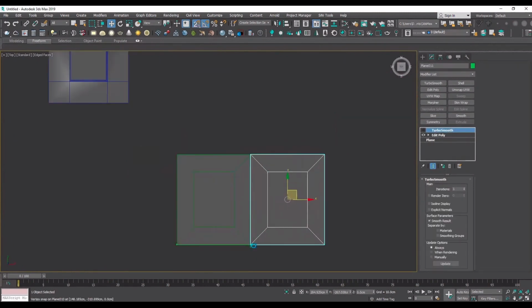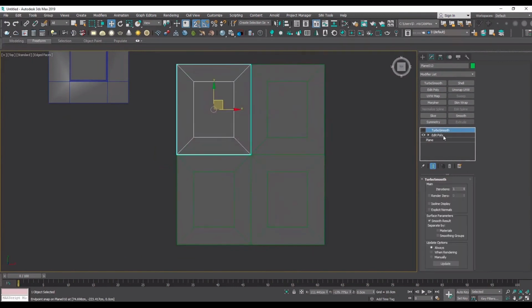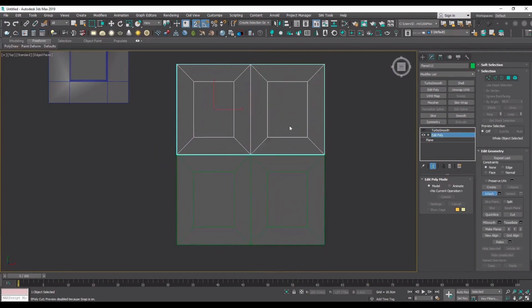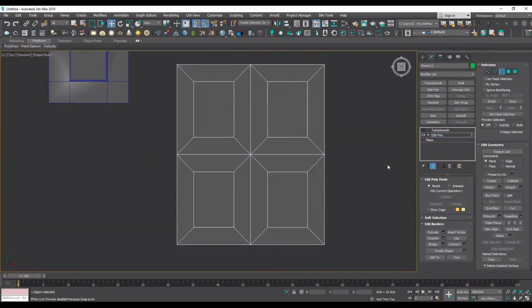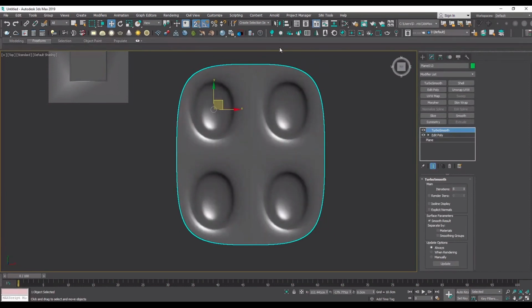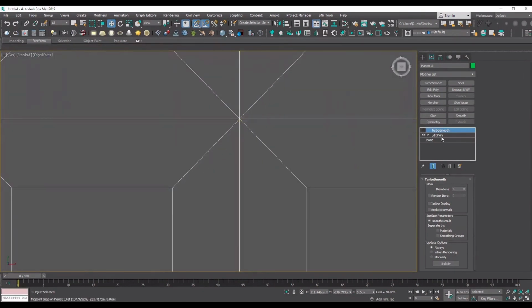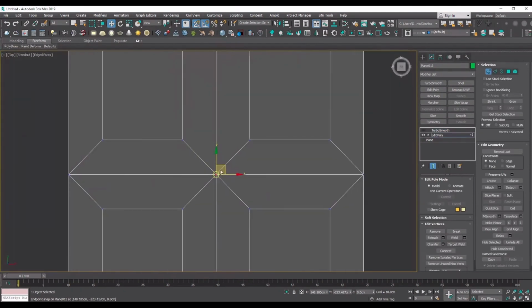Let me show you an example right here. If we copy our mesh and put them near each other, attach them together, and press 3 to activate border mode and Ctrl+Shift+V (weld) to weld them together. Now you see only the corners that have not been connected to something else are circular now. And when we limit the corners by connecting them to other things, they won't get distorted easily.